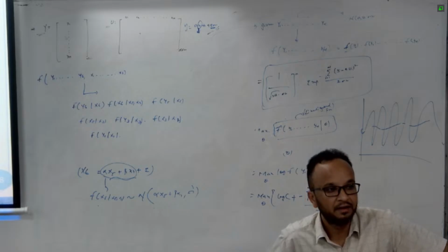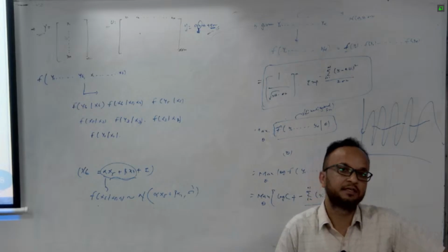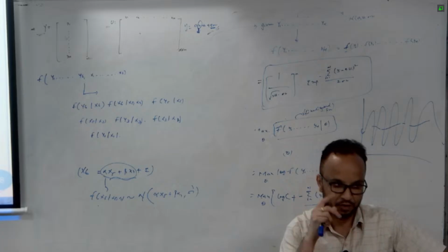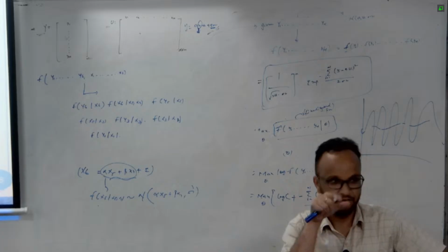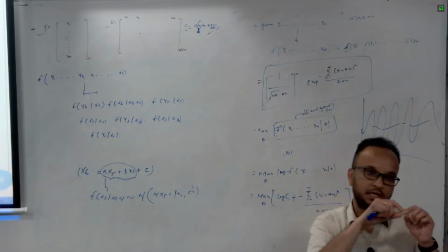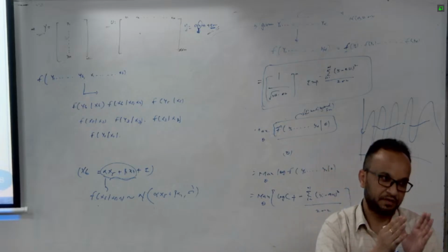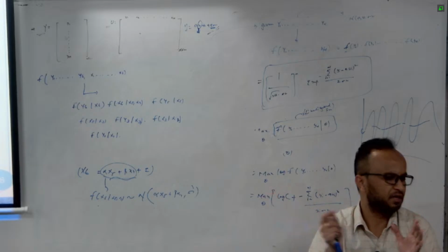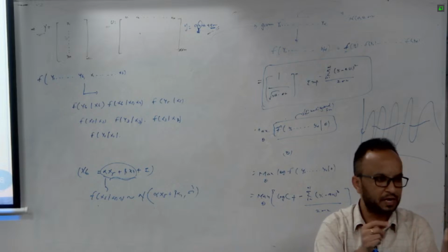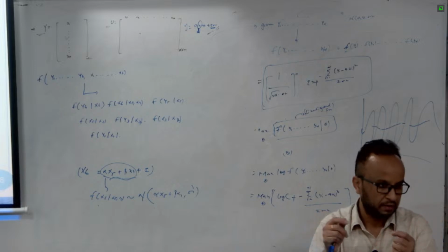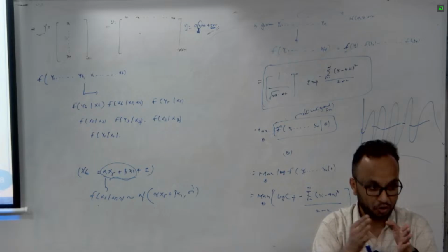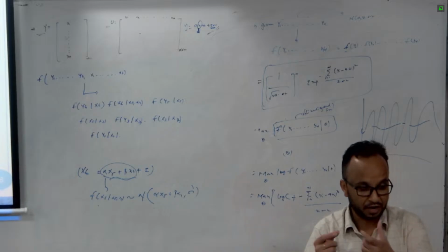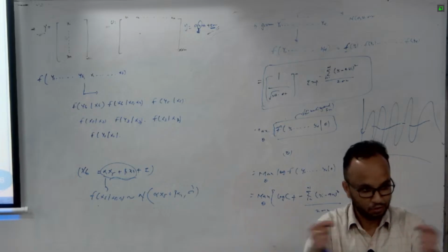There are two ways of filling the data, which we discussed in the morning session. One way is to use the previous value. Suppose the sampling frequency is high, with samples every 1 minute and some samples in between missing, so you are getting none. Then you can use the previous value or an average of previous values, a time series average. Suppose instead the frequency of data is very low: one sample comes at 1 hour, the next at 6 hours, then 7 hours. I can't use the previous value, because you don't know what is happening in between.